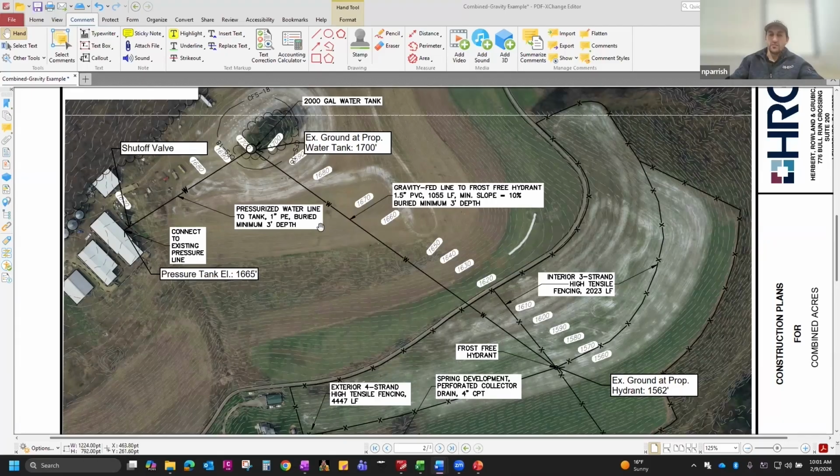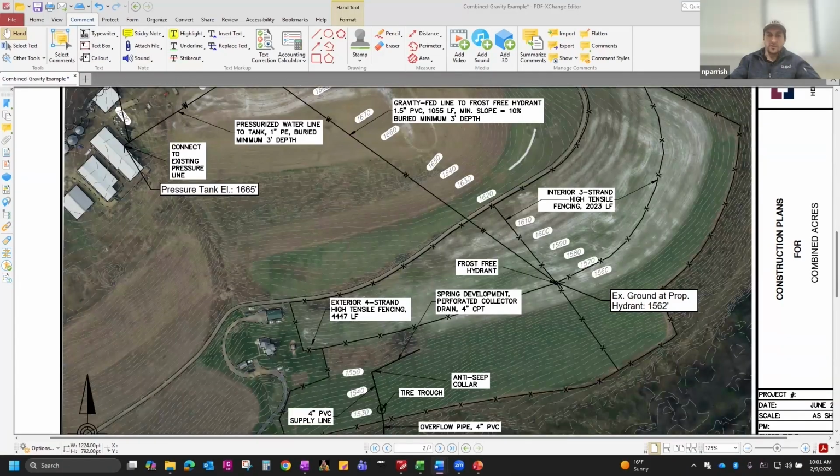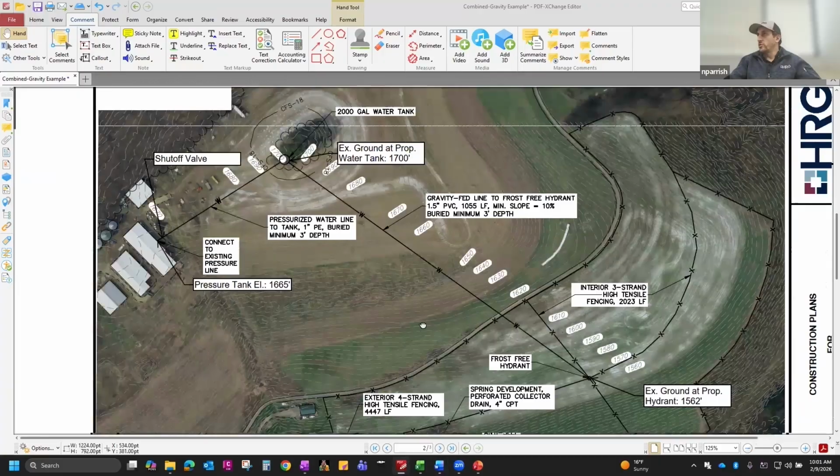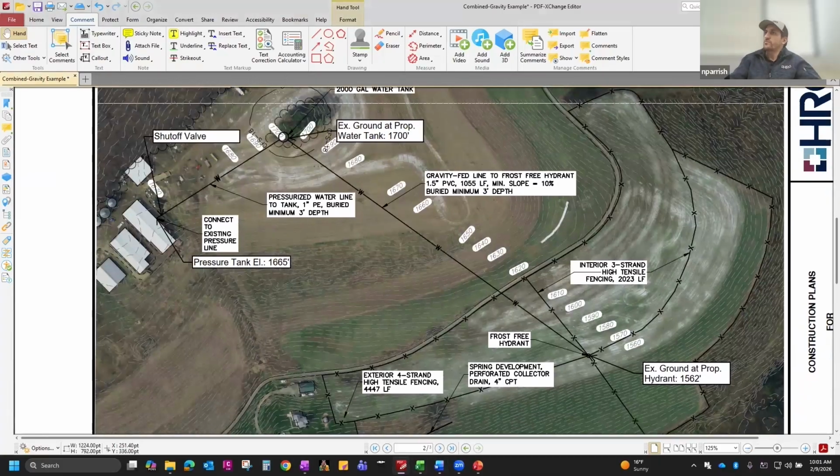Another reason being that we're checking that the pressure of the system does not exceed the selected material and that there is sufficient pressure to operate the system in the case that we may have a float valve at the end of the livestock pipeline into the water trough. So without further ado, we will get started here.